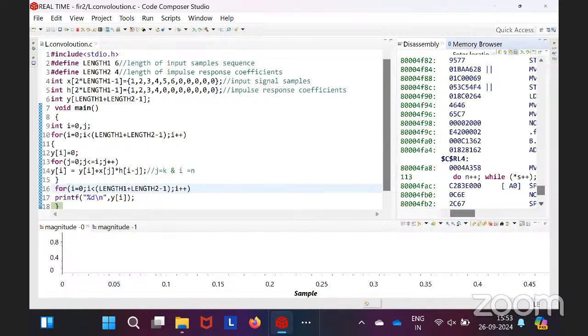If I remove this printf and stdio.h, then I can reduce my computation time here also. It's only used for debugging. Otherwise, in regular embedded C, it is going to be ANSI C that we use, and I don't have any IO operations there. Clear screen and other such options are not there in ANSI C.